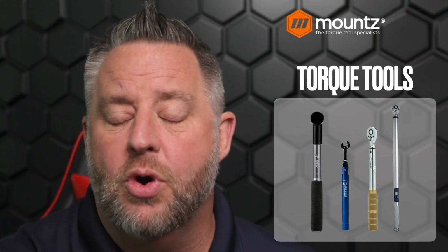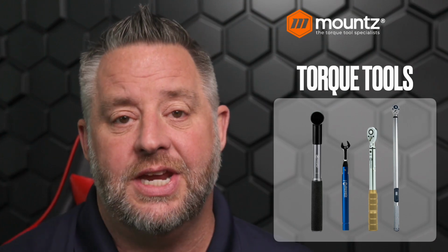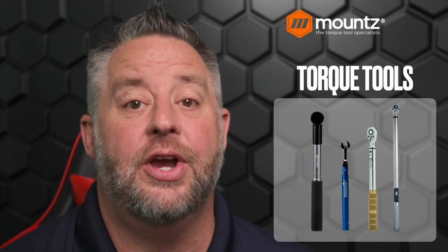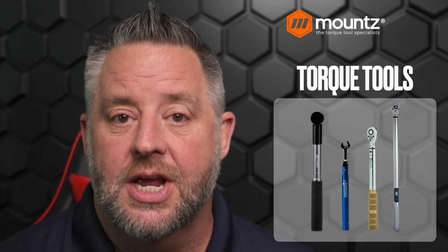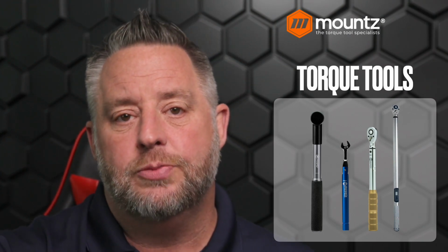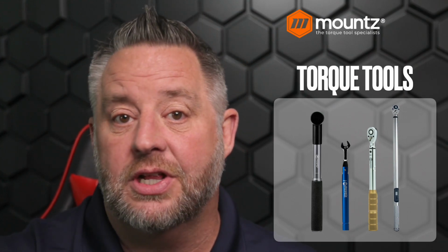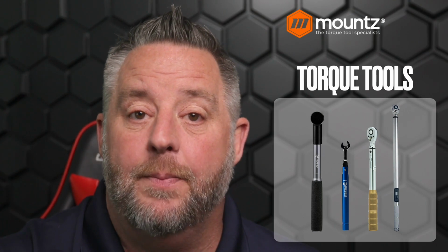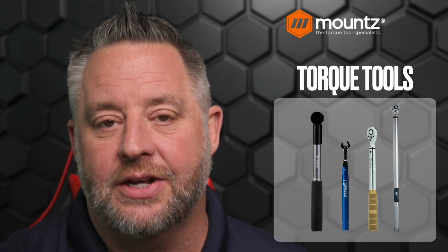The most widely used wrench around the world. The only issue with the click wrench is that it is very operator dependent on the final torque that is achieved. Because if that wrench is being used by the operator and the operator doesn't hear the click, feel the click, or see it, and they keep pulling, they're adding additional torque to that assembly.